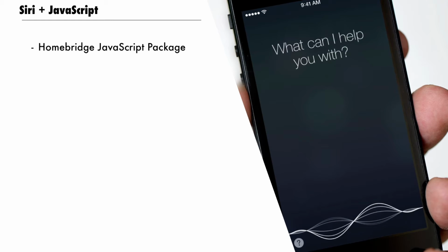So let's say you have a smart sensor in your living room. You build your Arduino, you connect your temperature sensor, and you connect a Wi-Fi module to it. You have to make sure that somehow your Arduino project connects to the Wi-Fi. To do that, you can use the NodeMCU, which I showed you earlier, the $3 Arduino compatible board, which can straight away connect to the Wi-Fi because it's got a Wi-Fi chip on it, but at the same time it can connect to sensors.